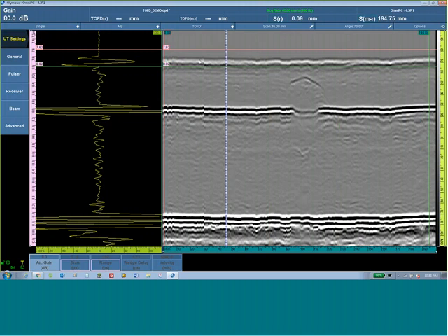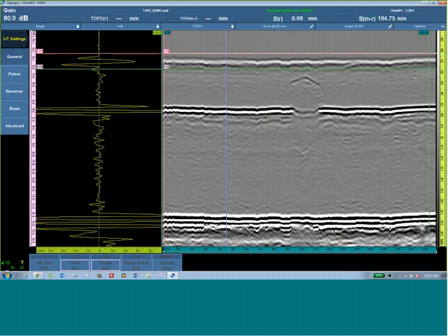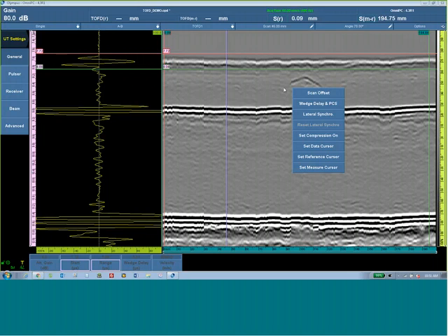We can see the scanner's a little jittery; there's a little bit of difference in the microsecond arrival time. Prior to doing a synchronization function, I'm going to make sure there are no surface breaking defects. If I have surface breaking defects, the lateral wave synchronization function will hide and obstruct them. So this function is available from a right click, or press and hold on the touch screen, directly on the B-scan: lateral wave synchronization.